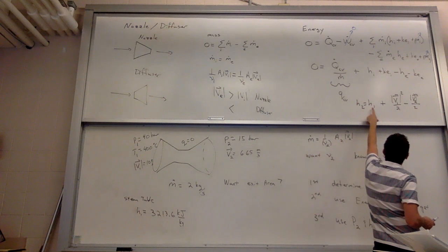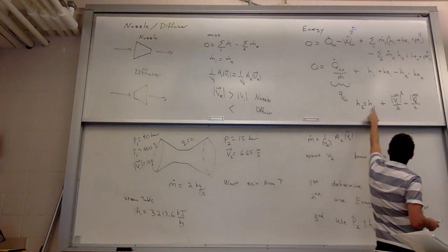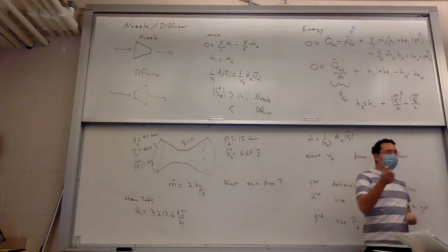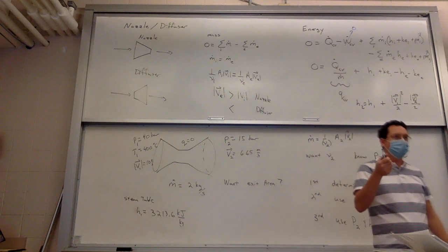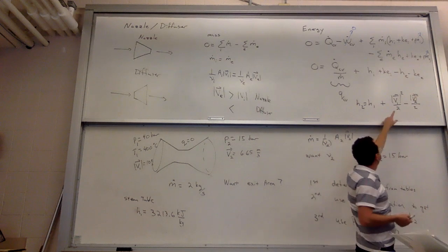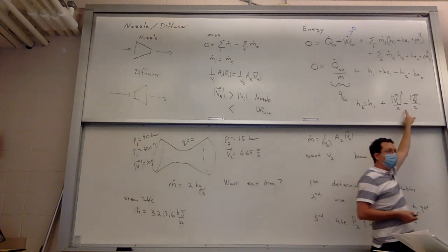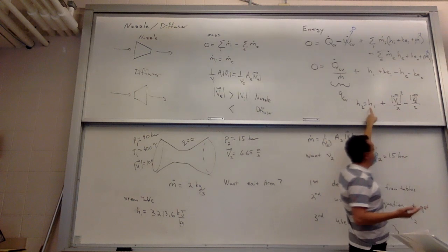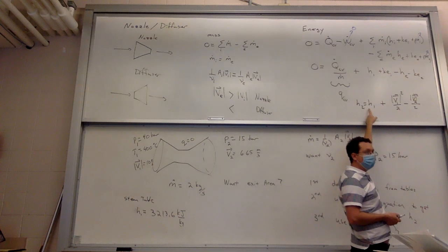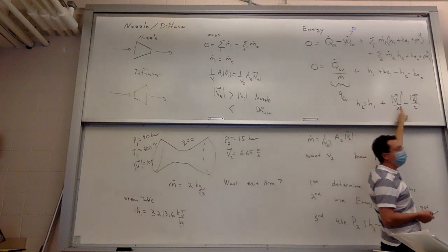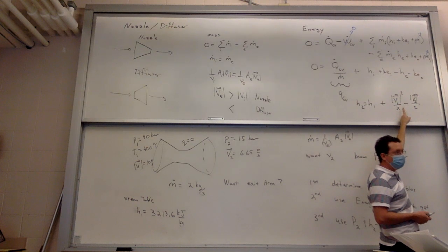What are the units? If I do velocity in meters per second, then kinetic energy is going to come out in joules, right? Normal physics 1 stuff. But the enthalpy is in kilojoules. So I need to get this term into kilojoules, so I need to divide the number by 1,000.